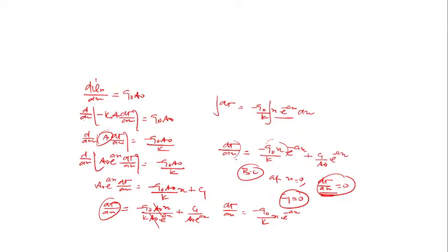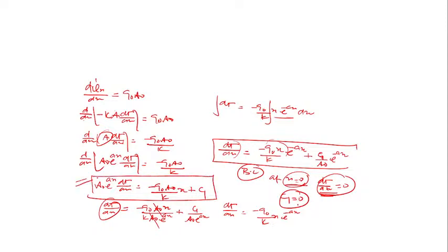dT/dx is 0 only at x equal to 0. This I did to put the boundary condition, madam. That makes c1 0. Actually, this is your condition. Otherwise, you can come to here. This, madam, c1 is a constant. How can I find the constant? By using the boundary condition. What boundary condition do I have? At x equal to 0, dT/dx is 0 because well insulation is there.